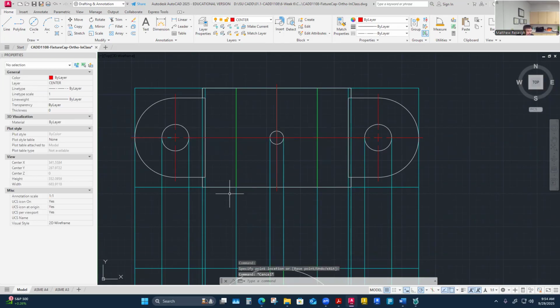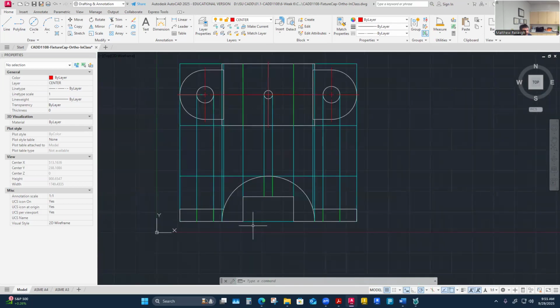Now I feel like I've just got better vertical and horizontal alignment. I really show the radius to the center, that concentric nature of the holes and the radiuses on the part. Then they also are in line with the middle of the part here and the middle of the part here. But I still need to add dimensions when I go into those locations. Remember that even though I show that alignment, I still need to probably define it. So with a dimension, yes, it's good to show it, but maybe I need to dimension from center over to those features just to lock it in.